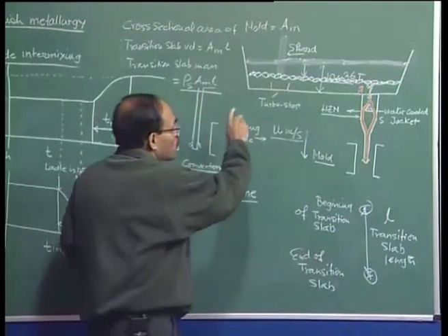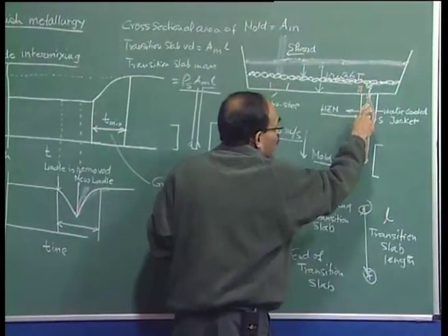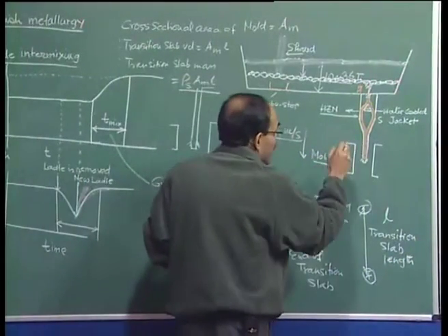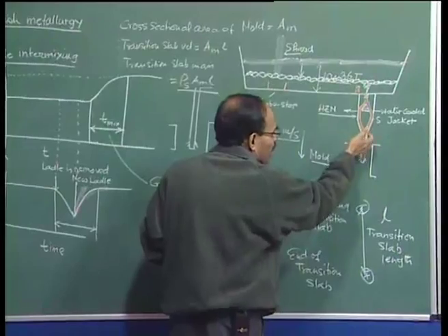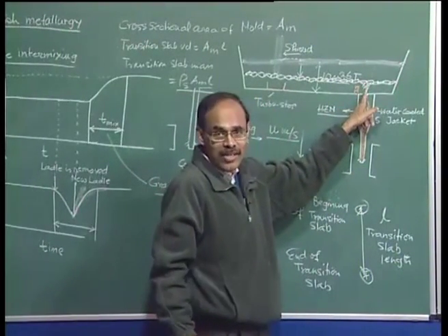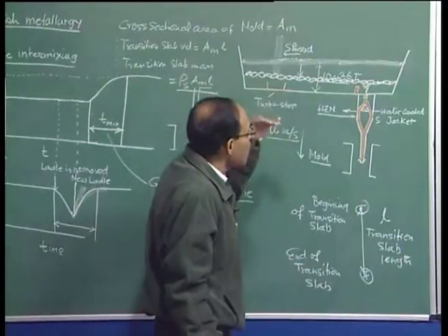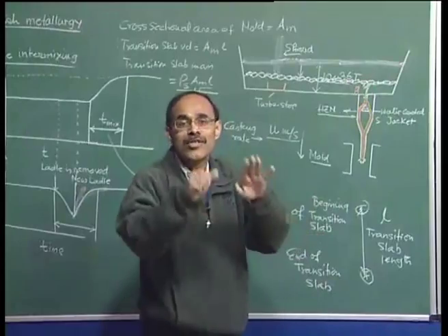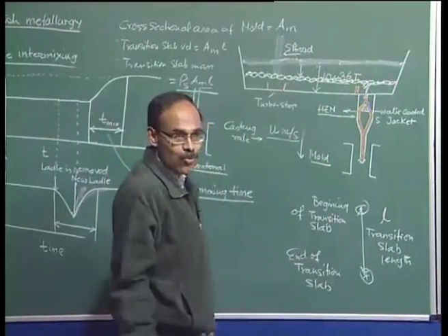Okay? If you don't stop the casting, what happens? Slag will be entrained, and this slag, which is oxides, is going to make steel weaker, and as a result we can have innumerable problems. And of course, nobody is going to buy steel which contains a lot of entrained slag particles. So, the moment slag starts to be entrained into the mold, it is at that point that we say the casting of this particular sequence is over.